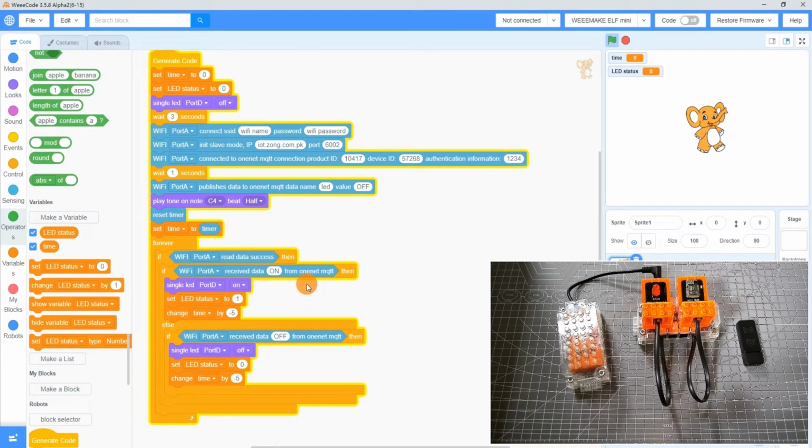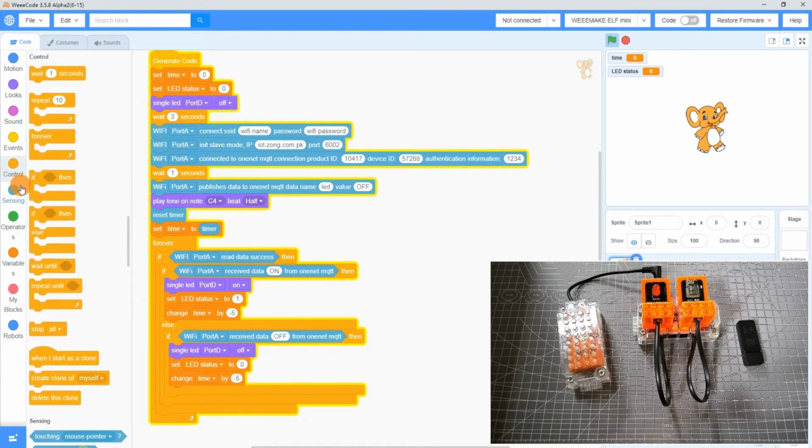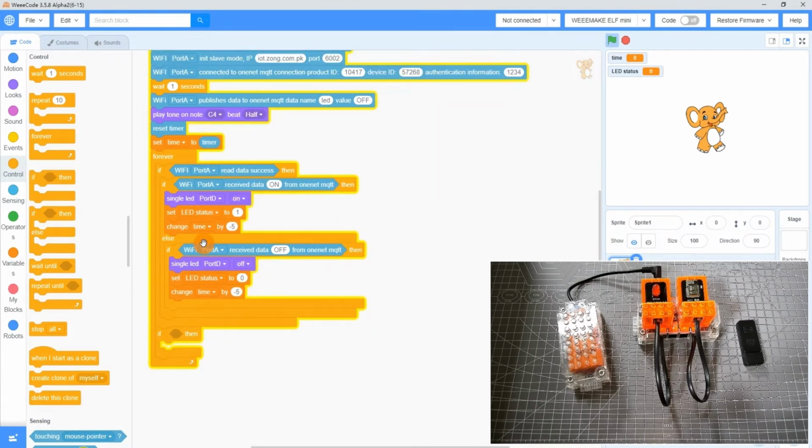Let Wi-Fi module send data to the IoT platform by every 5 seconds to maintain connection between the Wi-Fi module client device and the IoT platform. We call this type of data as heartbeat, which is a package of data sent on a regular basis to stay connection.